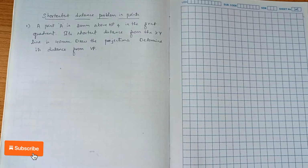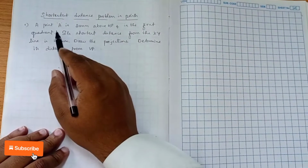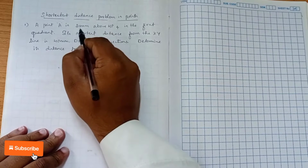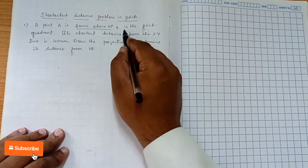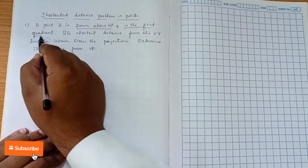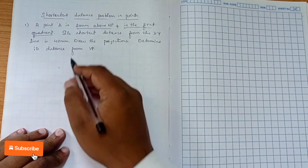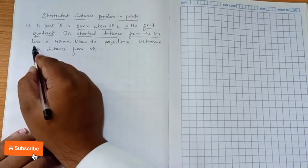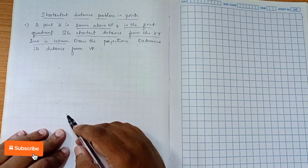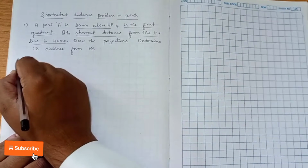Now we proceed to the question. You can see this is a shortest distance problem. A point A is 20 mm above HP. Above HP means it is the front view, so we get one view, and it is in the first quadrant. That means we have to consider the first quadrant, that is VP above XY line and HP below the XY line. And then he is mentioning, its shortest distance from the XY line is 40 mm. That means an arc distance of 40 mm you have to consider to construct it, and then draw the projections and determine its distance from VP. So you all understood, right?